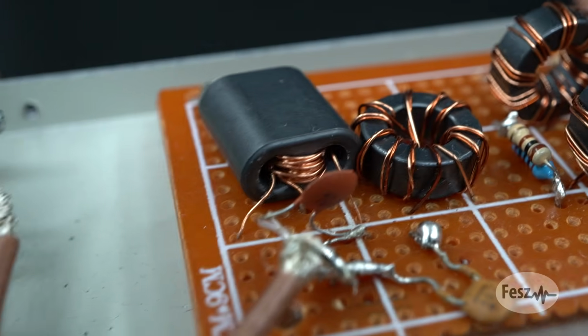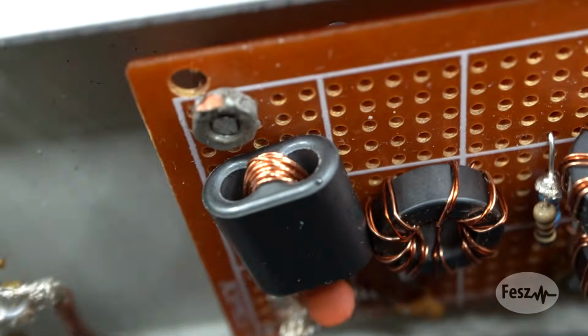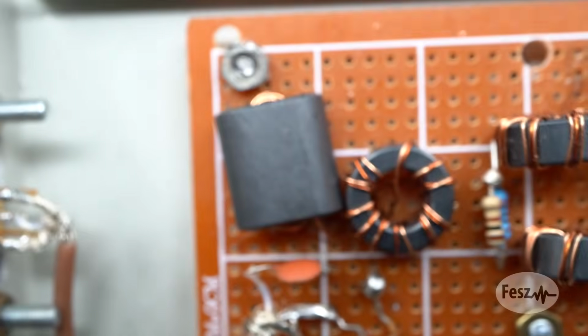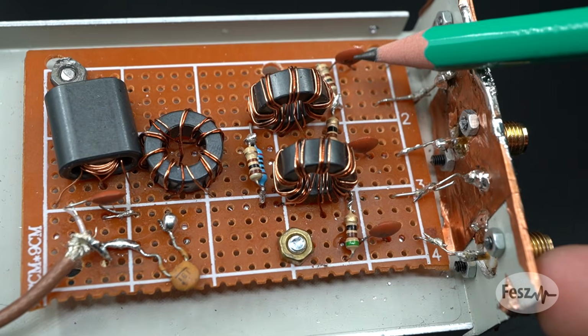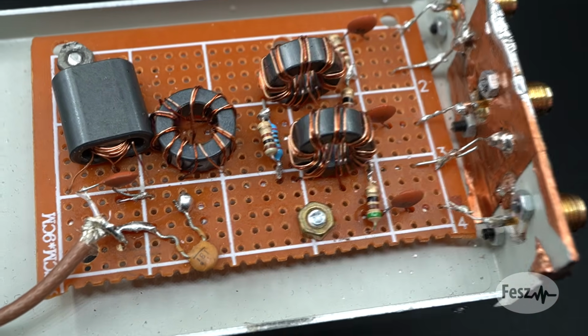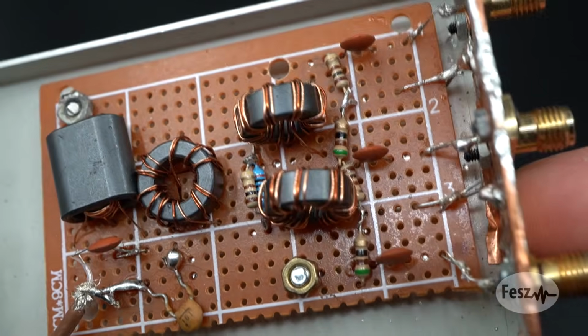For the impedance matching transformer, it had a non-standard ratio of turns, so to try and improve coupling here, I just put it into a binocular core. And well, to finish it off, there are a bunch of capacitors and the isolation resistors. And well, that's about it.